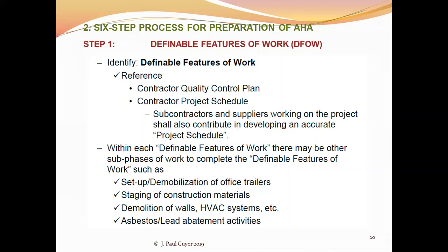Setup of the construction office trailers, staging of construction materials, where the borrow material is to be stored, where the lumber is to be stored, where the waste material is to be dumped, etc., etc. Demolition work, another task, and then if there's asbestos and lead and all of that stuff.